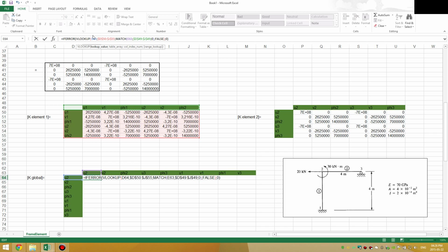And next, my row number or row degree of freedom will always be in column D in Excel, so I can just put a $ before the D, and then this row or this entry will always be in row 63, so I can put a $ before the 63, and then I have fixed everything. So that is my completed statement for the first element matrix.